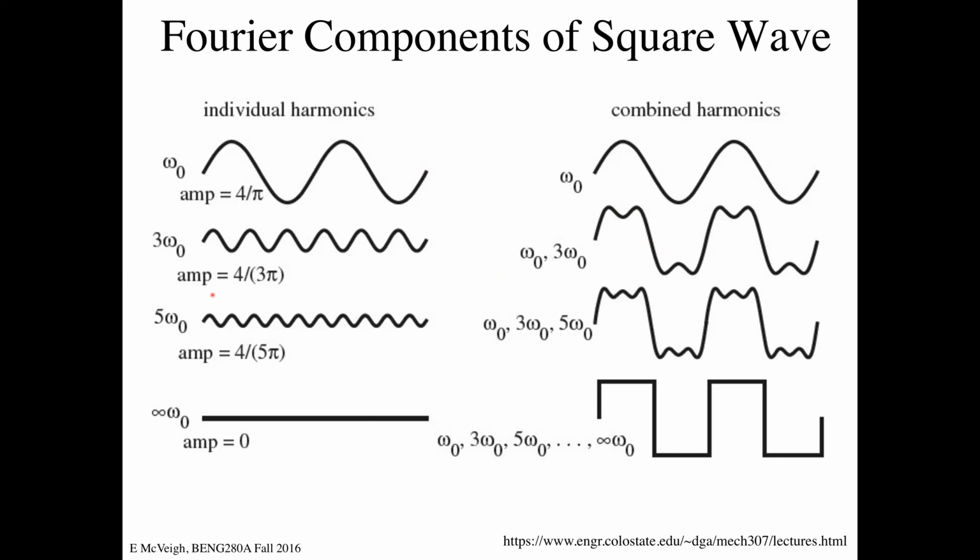And then I jump to 5, and its amplitude is 4 over 5. So it's smaller in relative amplitude than the primary or the secondary. And then I get 2 bumps on the extrema and a sharper edge again. And so as I add higher and higher frequencies, we will eventually get as close as we want to this square wave.